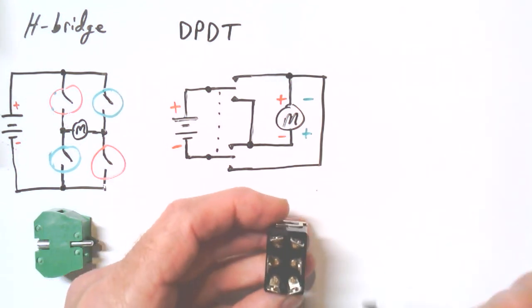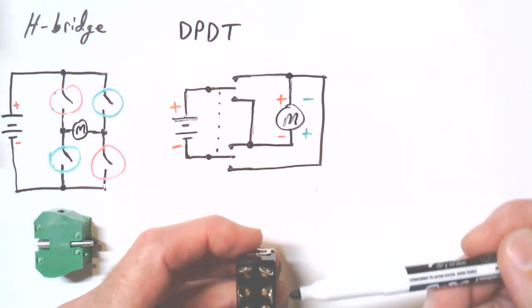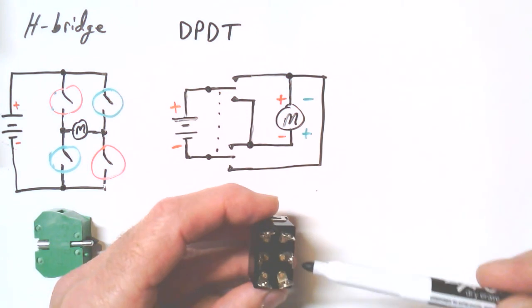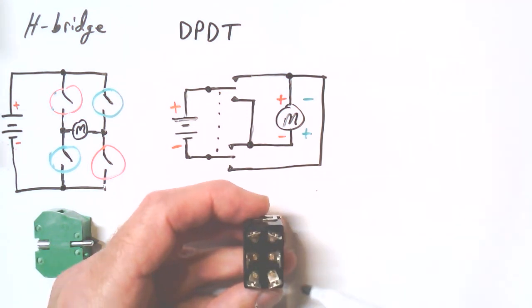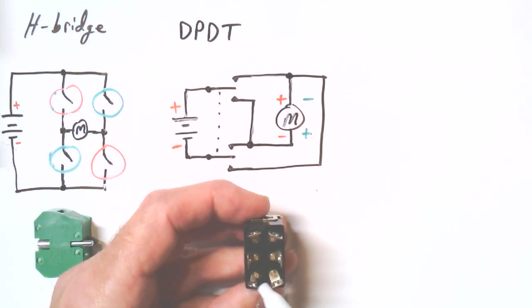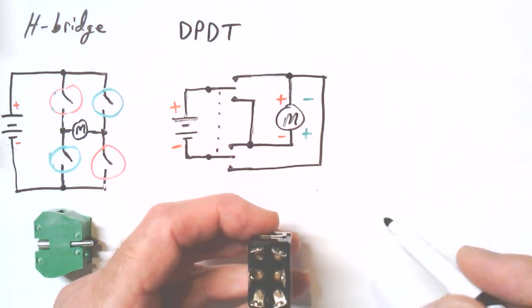But here, finally, all that to just lead up to the fact that I wanted to tell you, if you actually are implementing with a switch that has this kind of pin configuration, which is the most common, the poles are here and here, you'll just see an X pattern. You'll see just a crisscross. These two will be wired together, and these two will be wired together. Let me draw that, and then show you what that looks like.